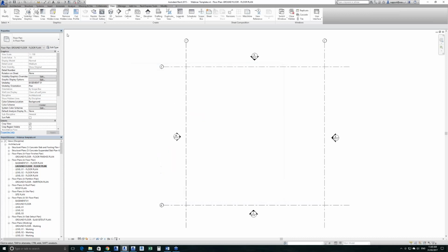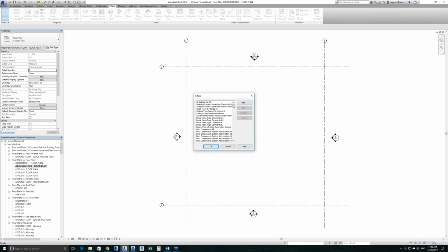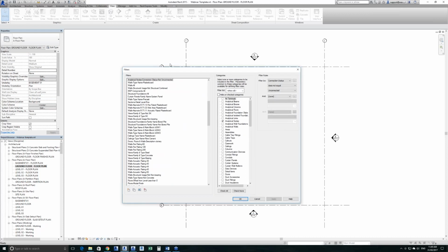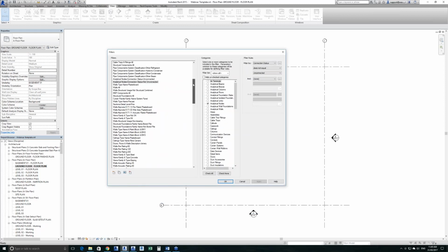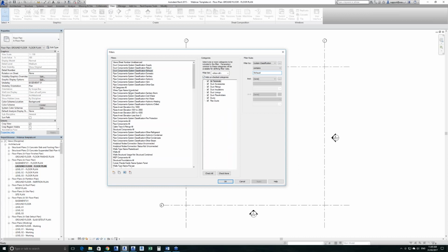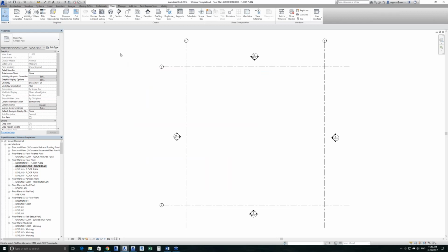So you'll see in here, I'm running 2015 at the moment, so unfortunately if I look in these, they're not going to be in any particular order, but as you know, 2016 R2 and 2017 list them alphabetically, so it's much easier to find the ones you want. But again, there's a standard naming system to these as well, so it's the family category that it applies to, followed by the parameter data and the rule that's actually assigned to it. So it all follows a common practice, so it makes things easier to find. Filters, so we did filters.